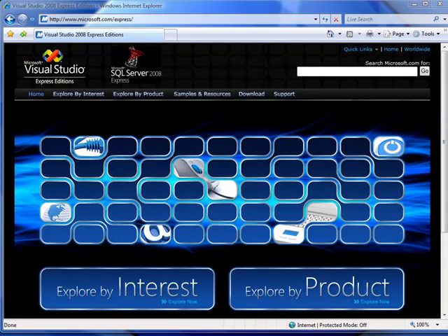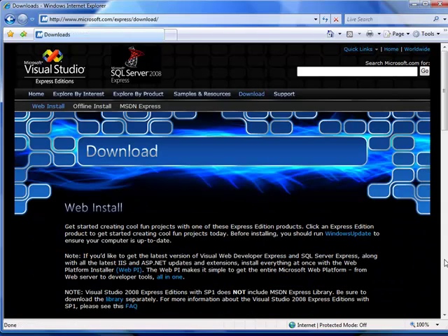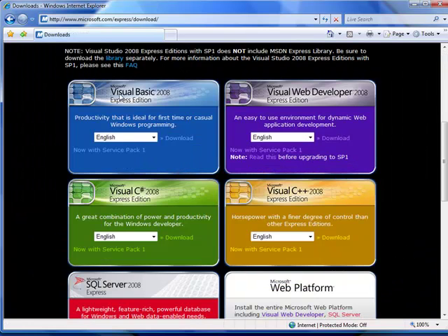In order to use OPC Controls.net to build an HMI application, you simply need Microsoft Visual Studio. You can use Visual Studio 2005 or 2008 or the free to download versions from Microsoft.com under the /express page. If you go to this page, you can select the download link, and there you can download the individual product features, Visual Basic 2008 Express or Visual C# 2008 Express.